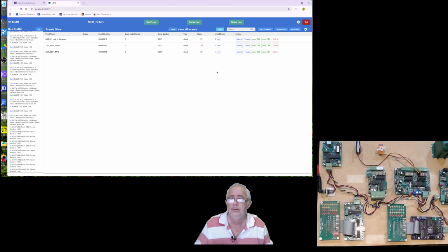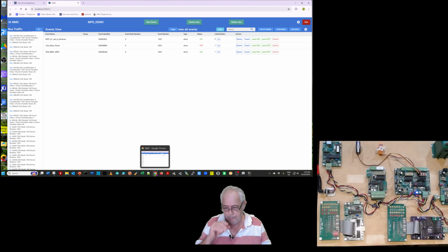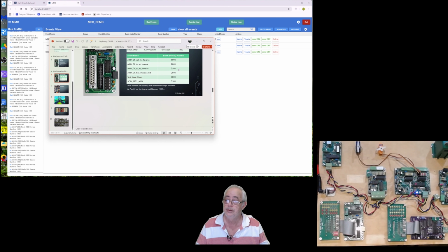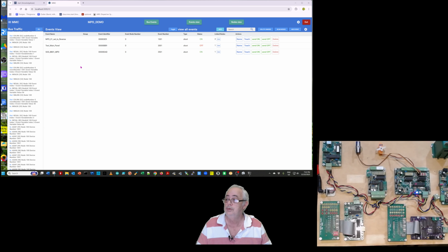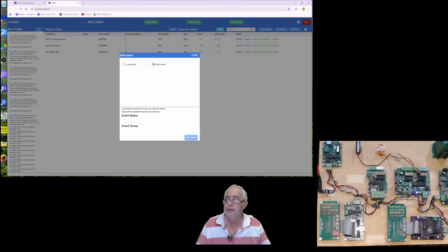Okay, now we want some feedback. So let's go and set up the feedback. We might actually set up the 3 feedback events in one go and then just go and do the association. So down here, I want to see what numbers I used. 2501, 2601, and 3001. So event view, add event, short event, 2001, if I remember rightly.